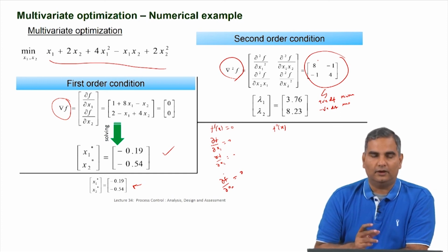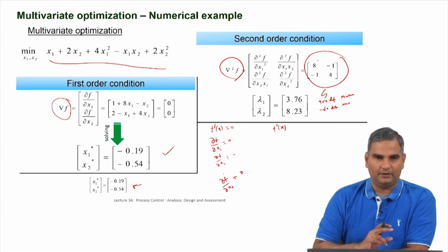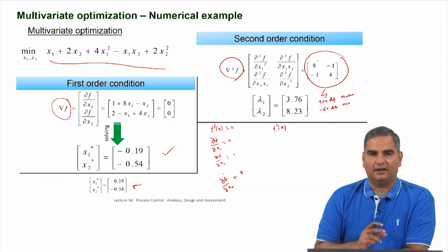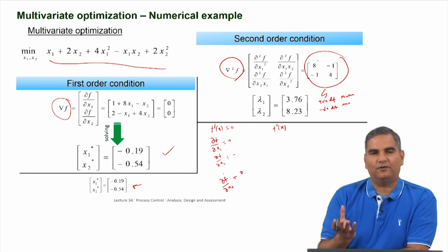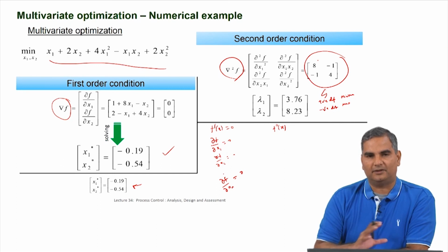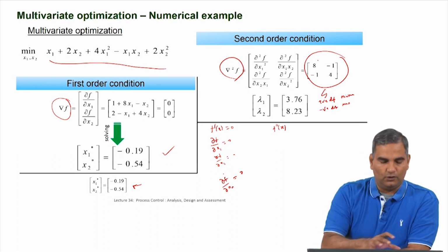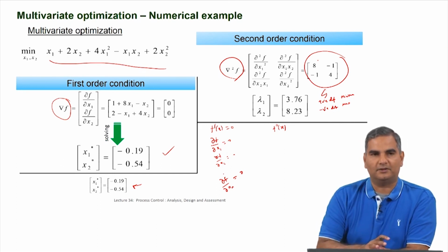Though they all represent the same control input, these are values the control input will take at different points. So, I am going to think of them as separate variables, and then I am going to formulate an optimization problem based on these variables. And I have told you that once I formulate an optimization problem, I can always solve and get a solution to all of this, u_k all the way up to u_{k+m-1}.